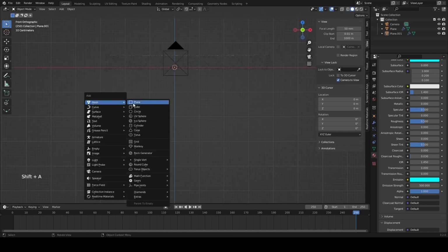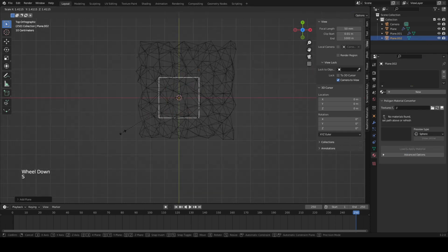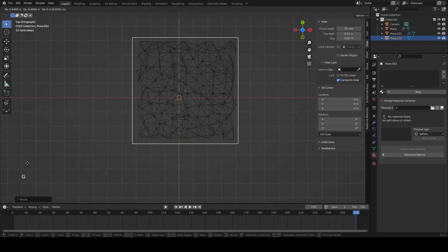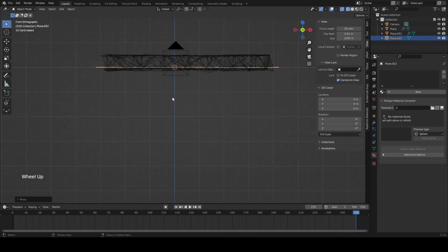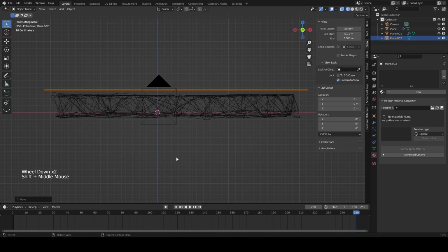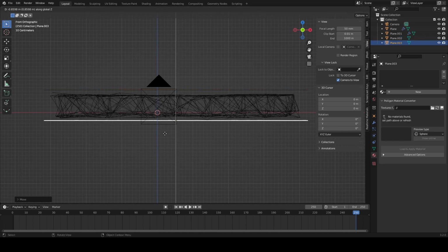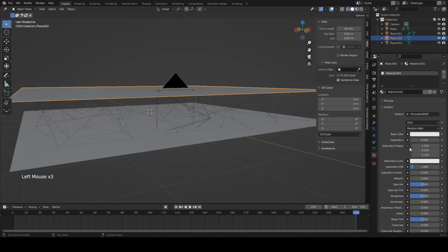And if we now define some planes around this scene to have some reflecting effects for the optics, we define this first plane and move it up, and we double it and move it down, and then we give that a material again, same color as all the other stuff, and some very low roughness, so it's reflecting a lot, and give it a name, blue plane.